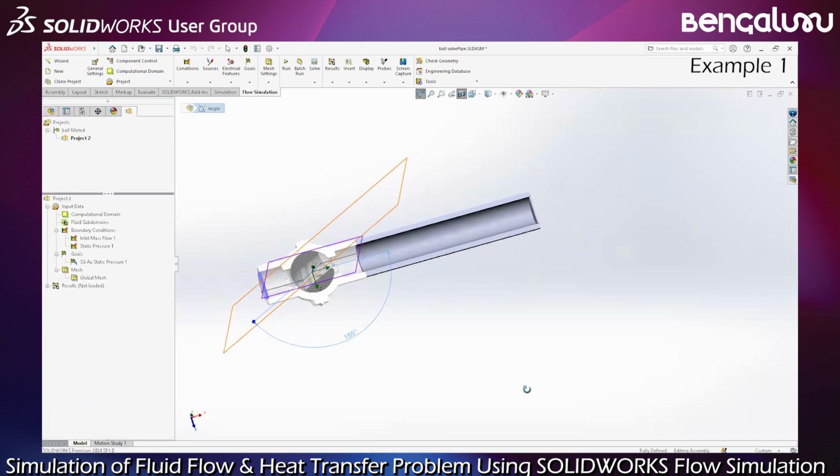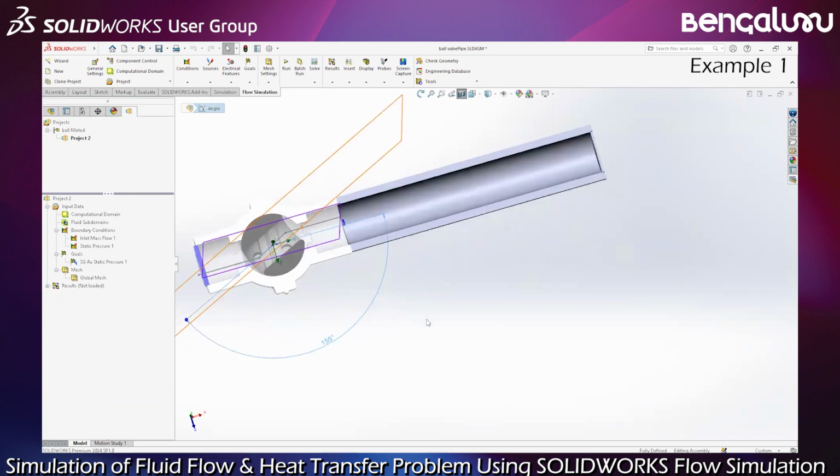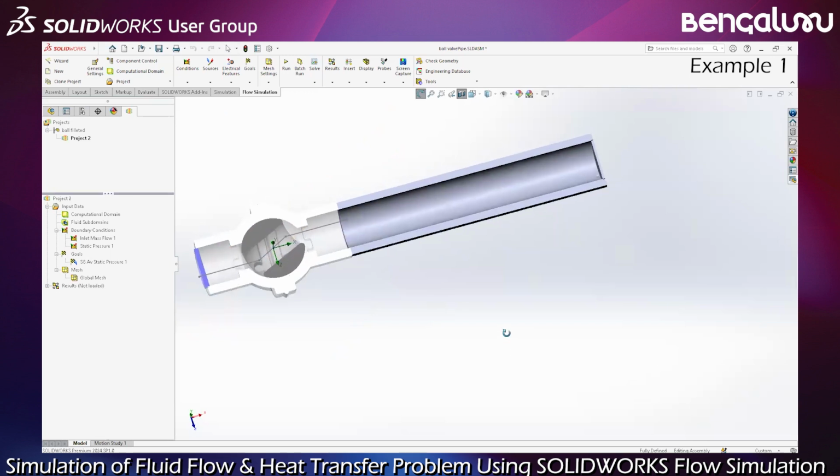Sorry. And why do I have to do this? Because if you remember, if I want to get good results at the outlet, it was still disturbed by the flow. There is a recirculation, etc. If I want to, for example, measure a good pressure drop, I have to extend the pipe, sorry, and make the measurement there, when I have a stable flow, okay?